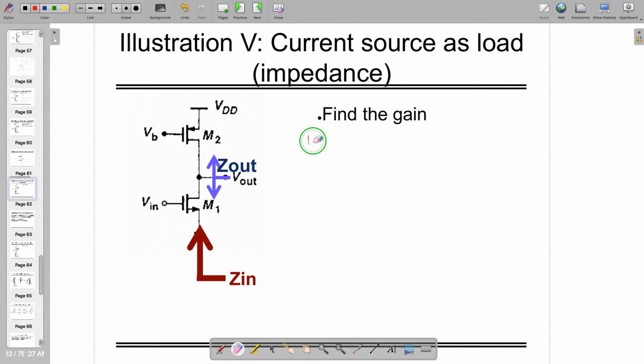Okay, let's start from a little bit lower side. What is the input impedance of this circuit? Do not consider this one. Forget about this one. Input impedance of any MOSFET circuit is infinite. Okay, so this is infinite. If you are looking into this, it's infinite. In the gate side, you are going to see only infinite.